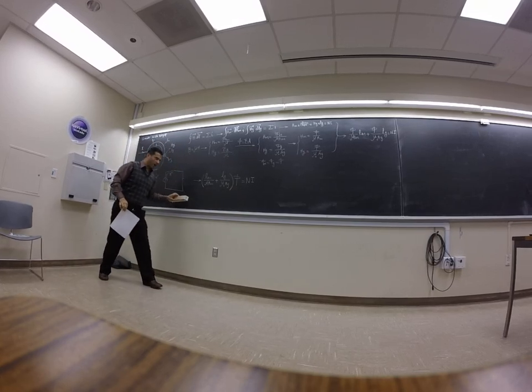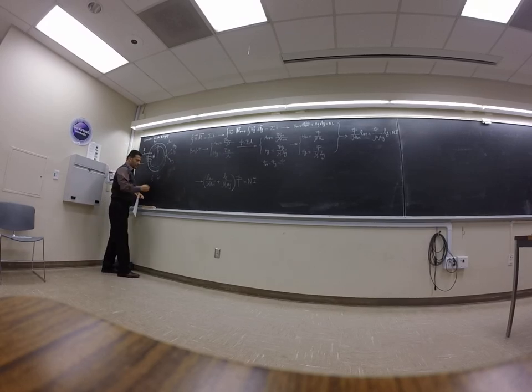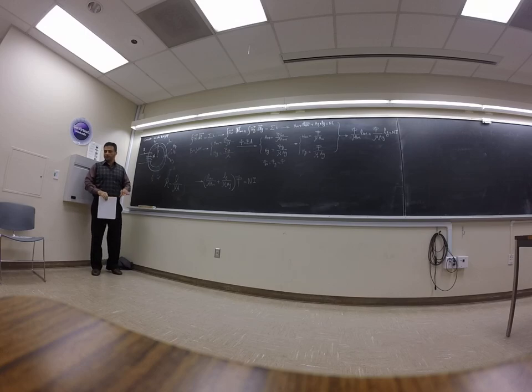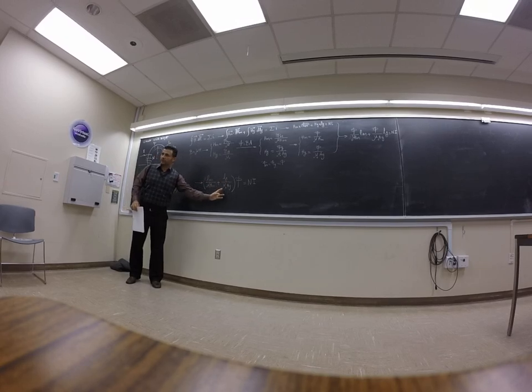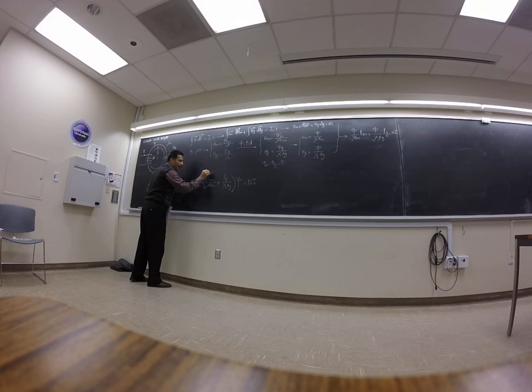Now just to remind you, what was the definition of the reluctance? Reluctance was L over mu A, right? So what is this? Lm over mu Am. This one is Lg over mu 0 Ag, right? Basically, this is the magnetic reluctance of the core.